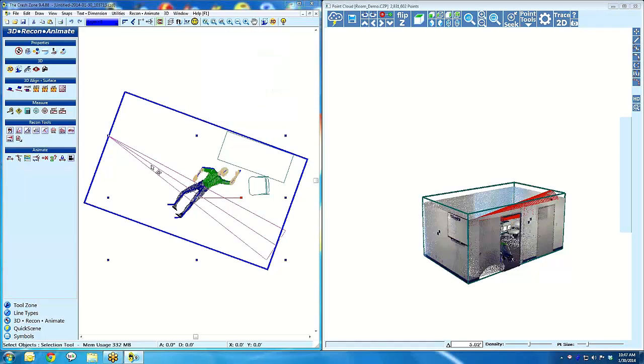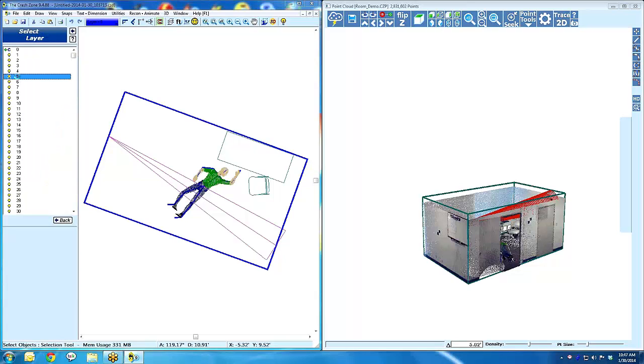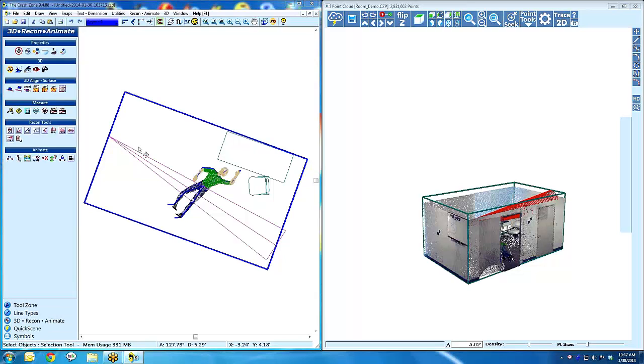Sure. You would just select the cone and go to properties, where we were changing color and thickness. Click on the layers button right here, hit show more layers, and I'll put him on layer 5. Now if I highlight it, you'll notice in the heads-up display or down in the command line that it says layer 5. This property is just to set layers and to select things and put them on layers.